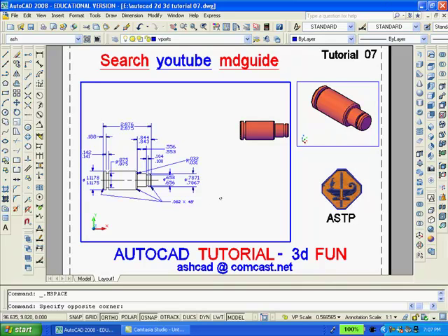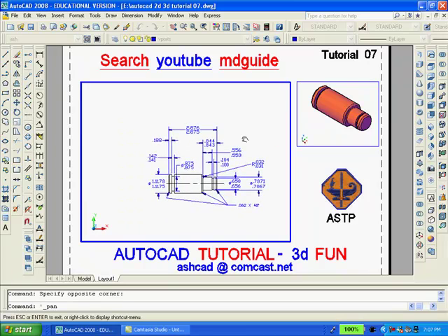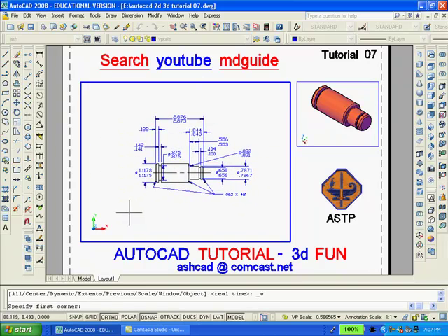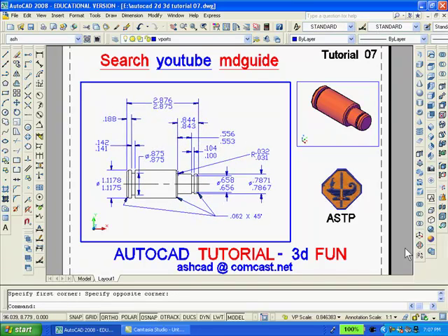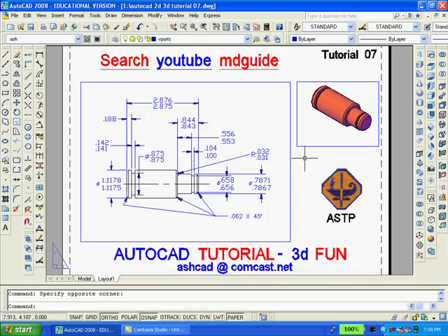Now pan so only the 2D drawing is visible. To accomplish this, it's sometimes necessary to move the solid. Then you double-click outside the large viewport to get back into Paperspace. Finally, if we don't want the large and small rectangles to be printed, we can go to the Layer dialog box and freeze the layer viewports where the viewports are located. That's optional. The drawing is now complete.